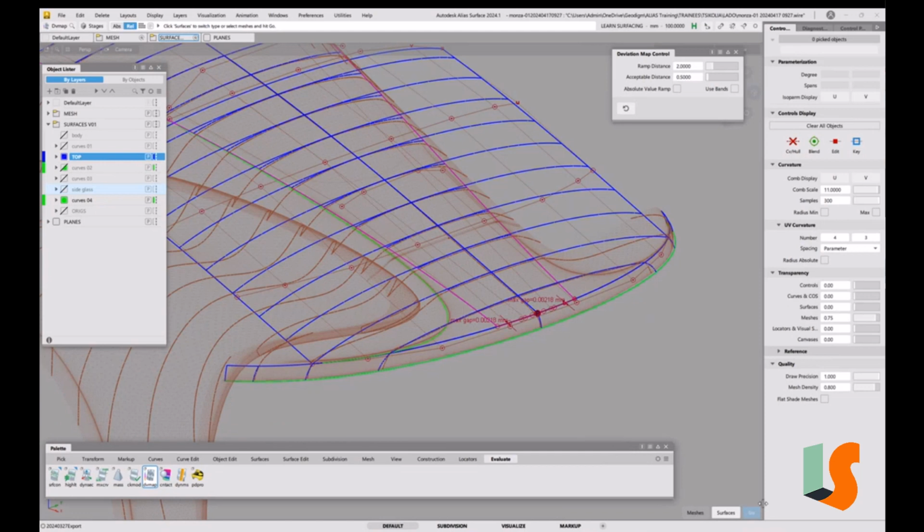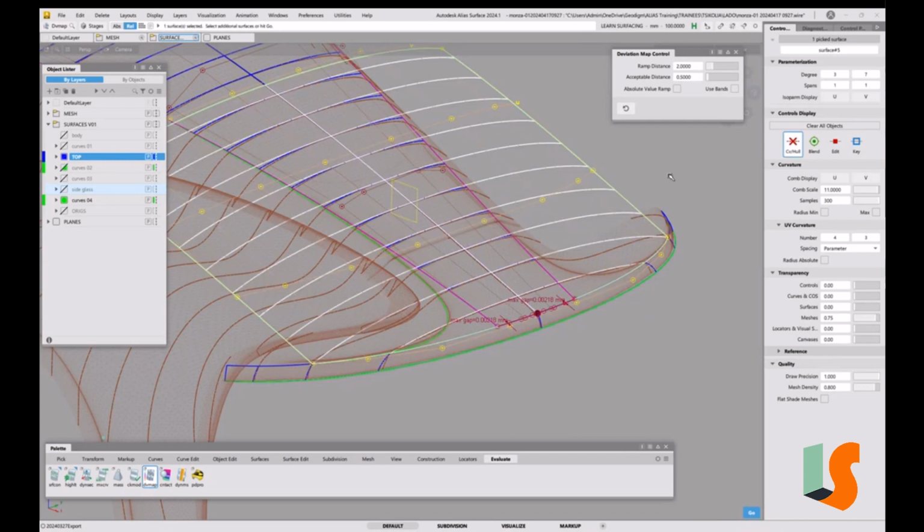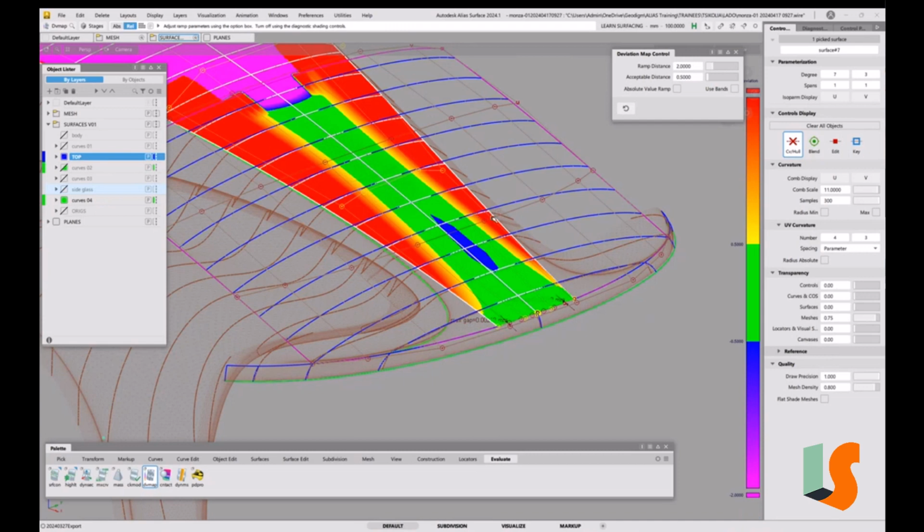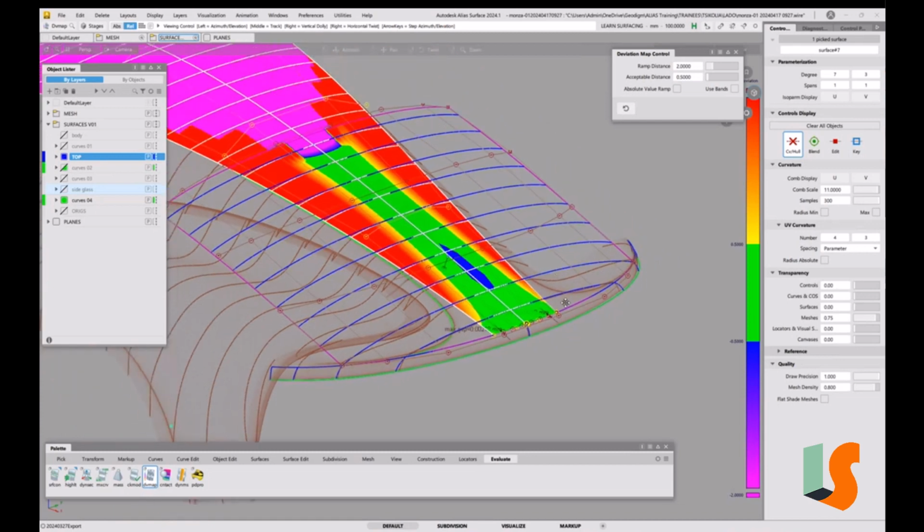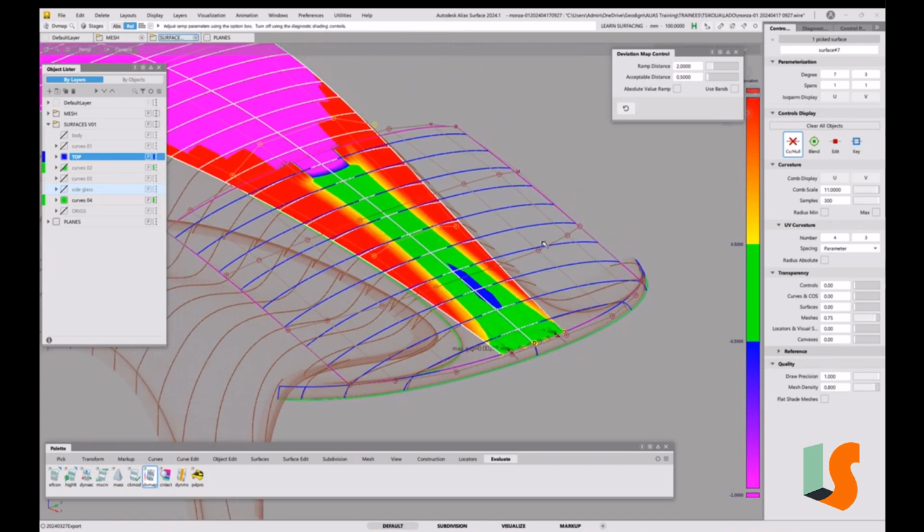The highlighting here is terrible, I think, because that looks to me as though it's looking for surface. But if I try and pick the surface, it doesn't pick it. So you have to pick on surface, which now looks like it's not highlighted, but it is. And then I can pick the surface, press the space bar, and wow, by some miracle, all that green area is within 0.5 of a mil. I was not expecting that to be quite so close, but that's great because it's pretty unlikely we get it any closer than that.